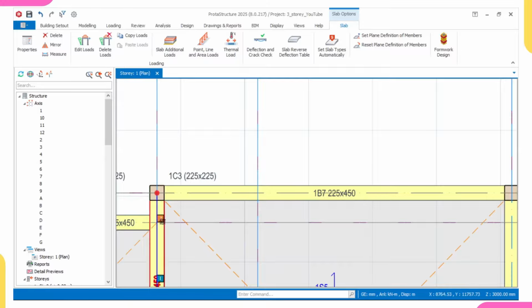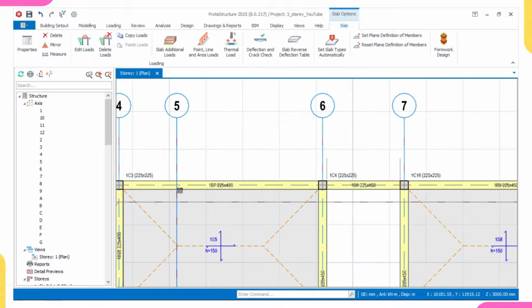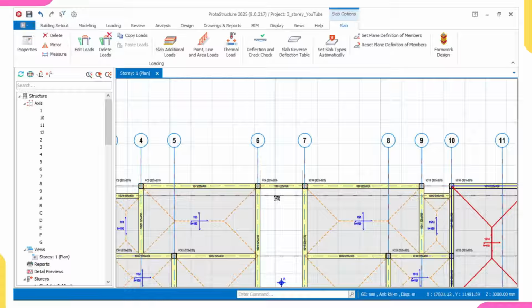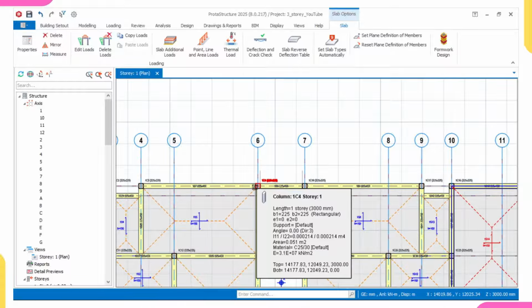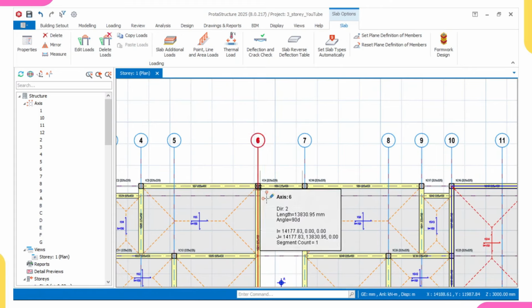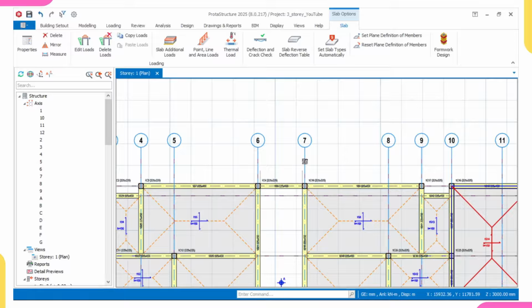So please, make sure you hinge your beam any time you are doing your design. So remember, we are going to hinge here and hinge here. We are not hinging here because summation of moment here is not equal to 0. We are also not hinging here because this is a continuous beam. So moment here is not 0. Here we'll be having something like this. It will come down and go up again, come down. We're having hogging moment here, hogging moment here.